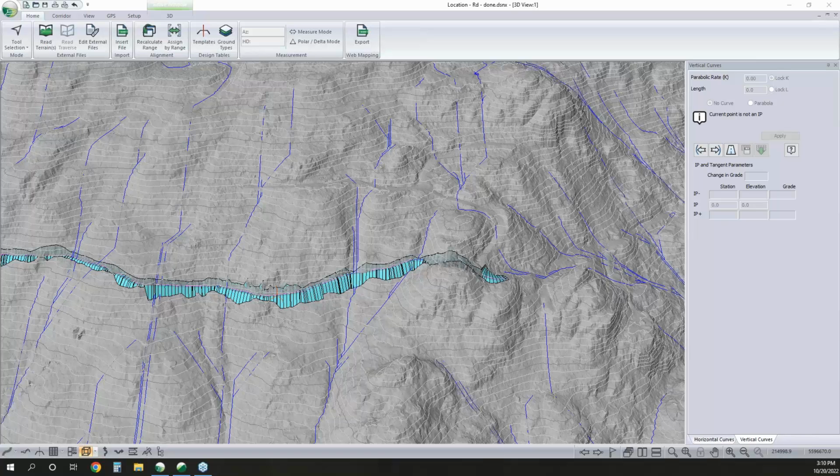And then we're going to switch over to our major pipes. So our major pipes will be those projects that we want to take a closer look at rather than just dropping in a culvert on our center line. We're going to look at the actual geometry of the streams that we want to place them on and model the excavation that we need in order to get that culvert down to its desired elevation, position it, and maybe do a little channel realignment as we do that. And then using corridor surfaces, we're going to put our road back on top of that channel that we've designed.